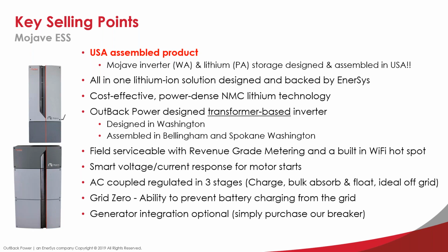The idea is you have a complete solution, right? So you'll get this thing, it all ships out together. Everything you need is in there. You've got a nice, cost-effective, power-dense NMC battery. So the form factor on this battery is it comes out about a foot from the wall. It's about 2 feet wide, and then the inverter is designed to mount directly over the battery. So yeah, the whole thing's about 7 feet tall, but you've only taken up 2 feet of wall space and 2 square feet of floor space, which for a system this size is about as small as it gets.